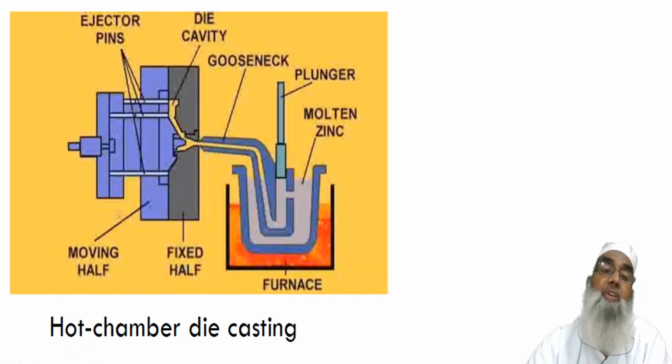After solidification, the product is taken out. This is the moving half, and when it is moved away from the fixed half, the product is ejected with the help of an ejector pin. But this type of hot chamber die casting is only suitable for low temperature metals.